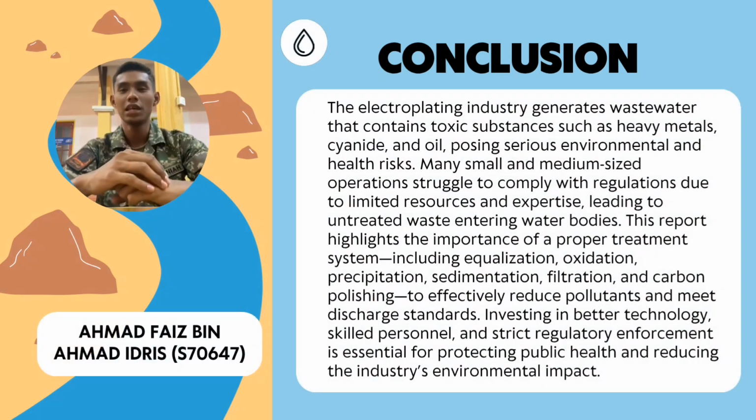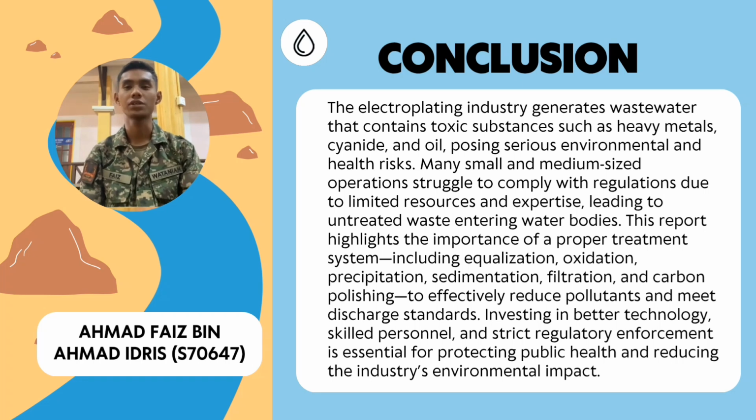In conclusion, the electroplating industry generates wastewater that contains toxic substances such as heavy metals, cyanide, and oil, posing serious environmental and health risks. Many small and medium-sized operations struggle to comply with regulation due to limited resources and expertise, leading to untreated waste entering water bodies. This report highlights the importance of a proper treatment system, including equalization, oxidation, precipitation, sedimentation, filtration, and carbon polishing, to effectively reduce pollutants and meet discharge standards. Investing in better technology, skilled personnel, and strict regulatory enforcement is essential for protecting public health and reducing the industry's environmental impact.